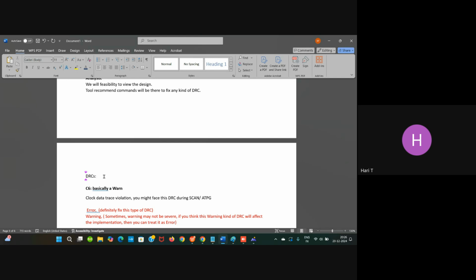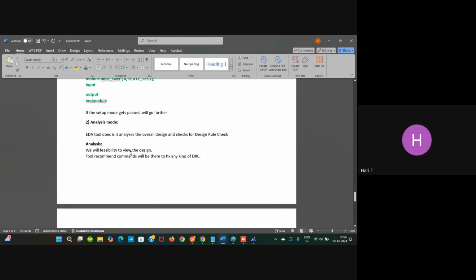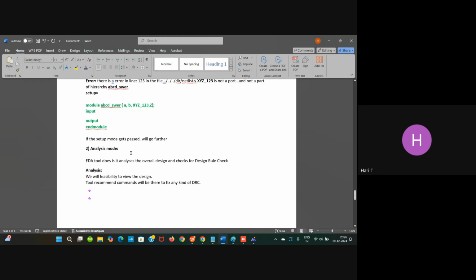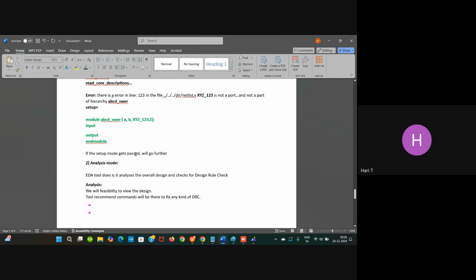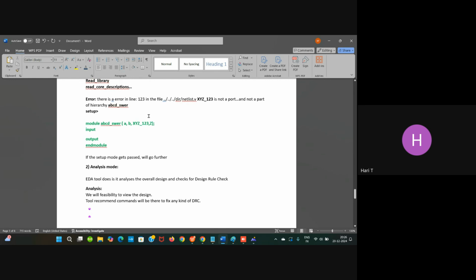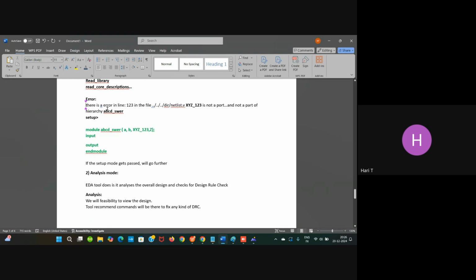You should learn Verilog coding in order to identify those bugs I mentioned earlier in the setup mode. There could be elaboration errors because we can't be sure that every input we consider during implementation is correct. The engineer should have the capability to judge that error, and we should report it to the RTL team.